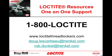Okay. How sensitive is chemical thread locker performance to different application variabilities? Again, our product tends to be very robust. The newer products were designed to be oil tolerant, and that's part of our criteria for developing products now. We recognize there may be residual oils left on a surface, again because the cleaners that were used in the past have been banned for other regulations.